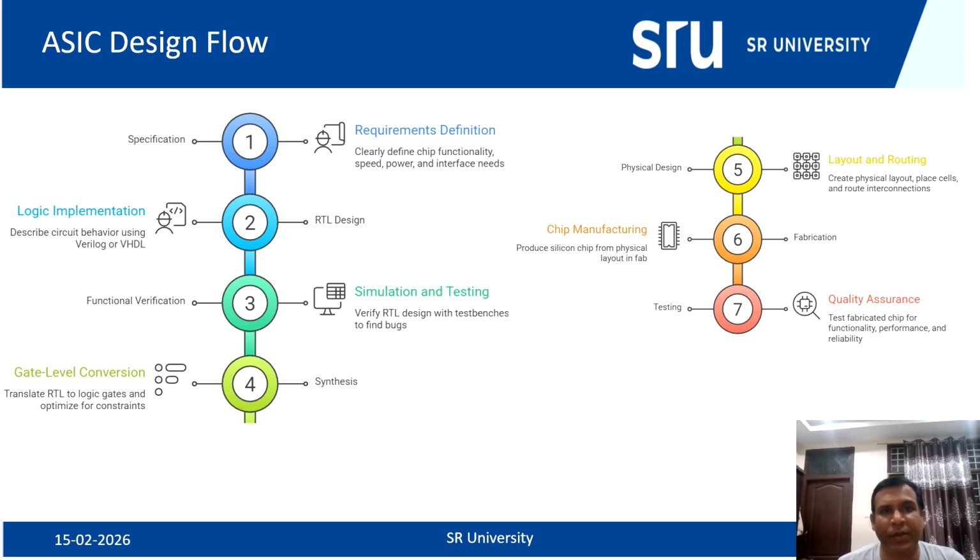This process uses different synthesis tools to translate the hardware description code into logic gates, such as different logic gates like NAND, NOR, NOT, AND, OR, XOR, XNOR. These are called micro cells, and some mega cells are also available in the standard cell library. It's like flip flops, different types of flip flop, SR, JK, then register, counter. These are the sequential circuits.